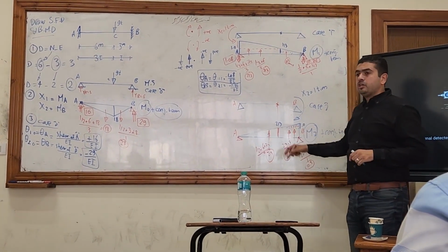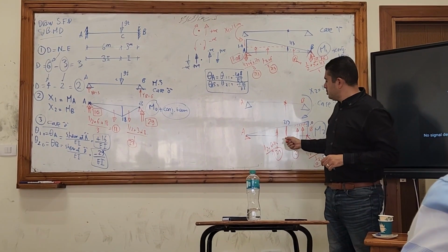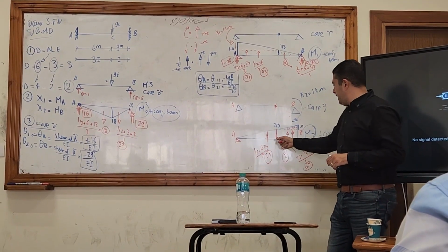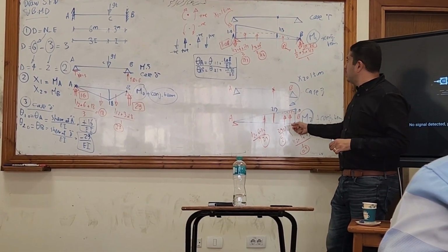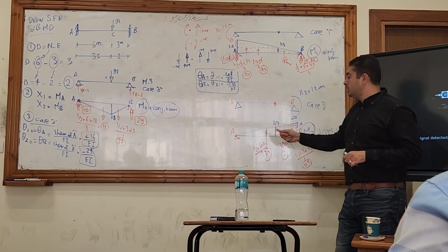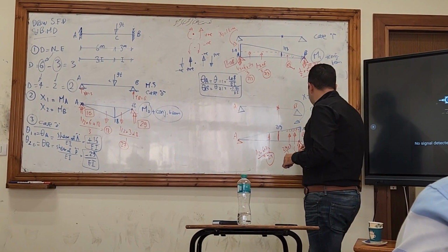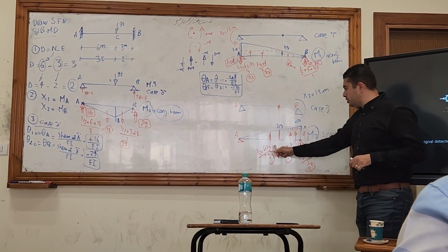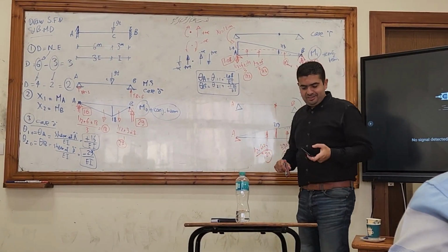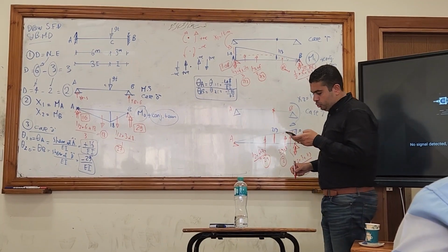Right? Let's calculate the reactions. Take a moment here. 2/3 times 4, 2/3 of the 6, 2 times 7.5, 6 and 1.5. Half times 8, 6 and 2/3 of the 3, which is 2. And then y times 9 equals 0. Here I can get the reaction at B, which will be downward because all of them are upwards. It will be 2.41.